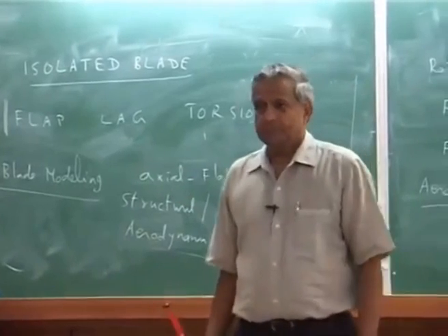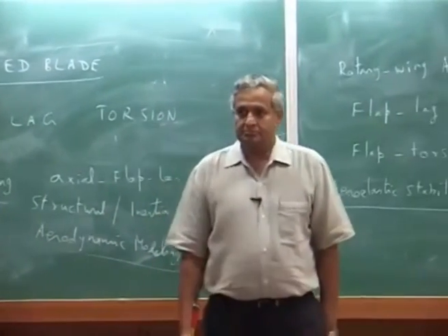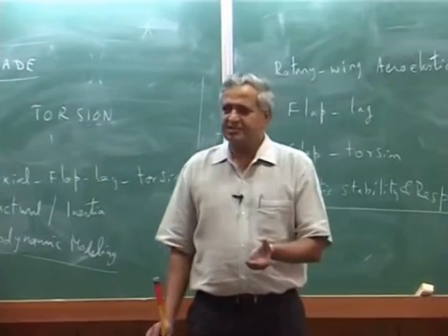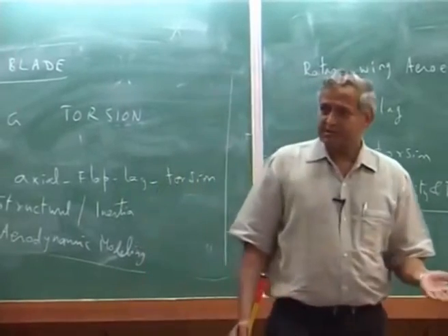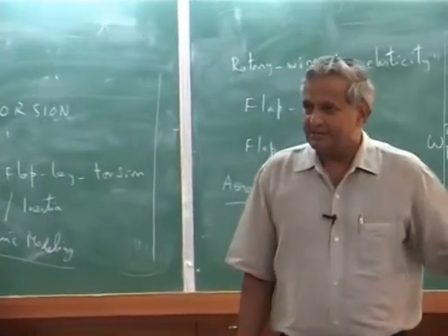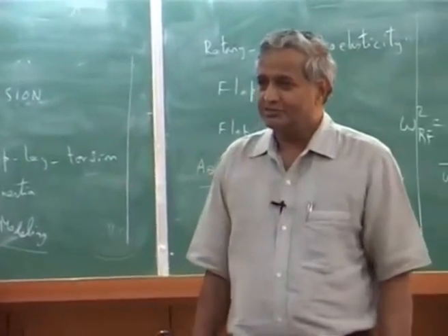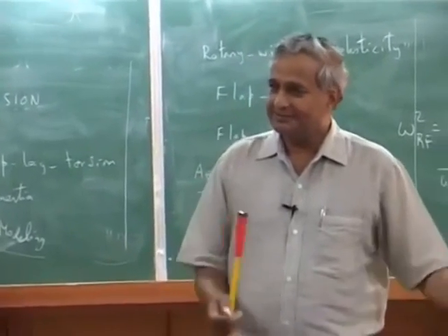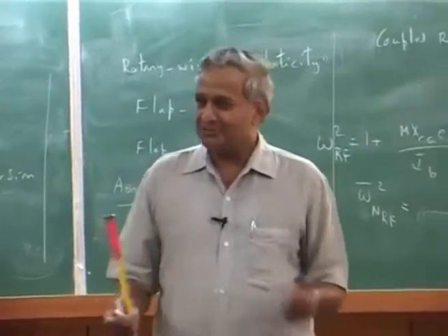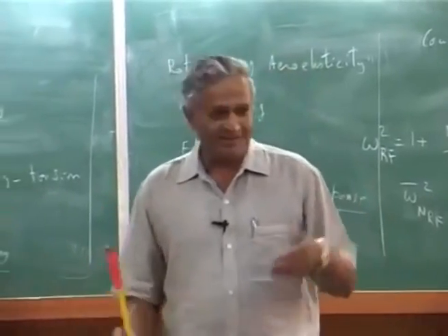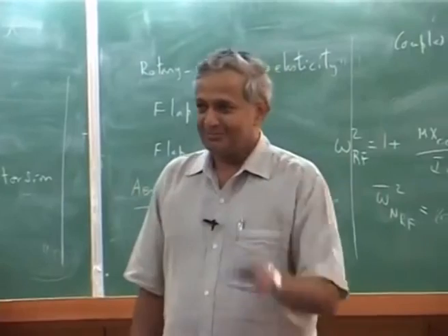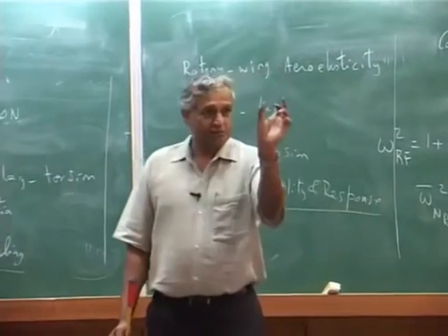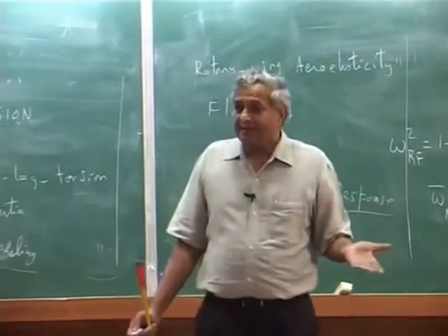But my question was, this K beta we are estimating, would it be of orders less than, say, EI, the blade stiffness? No, because dimension wise they are different. Dimension wise, this is Newton meter per radian. That is what? EI is what? Newton meter square. What is the connection? You can see one is a different unit, that is a different unit. You can't directly put it there. Of course, that affects this. You are looking at numerical value? No, not the numerical one.